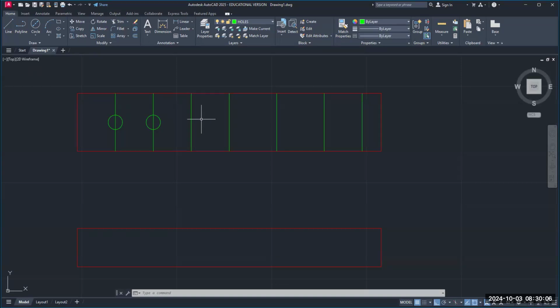Mr. Morris needs to look up the tap drill size, and I'm doing that right now on my phone. I'm looking up the tap drill size for 1/2-13. 1/2 is the diameter, 13 threads per inch.